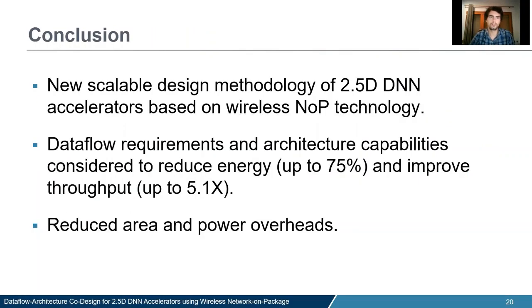So, as a conclusion of this presentation, we've presented a new scalable design methodology for DNN accelerators based on wireless technology. Specifically, we focus on the scale-out problem, that is, to increase the number of chiplets. And since electrical interposers are bandwidth limited due to the physical size of the chiplets, alternatively, we propose wireless interconnects by means of wireless Network-on-Package technology.